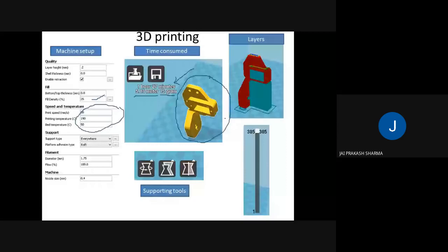There are a few tools with the help of which you can perform several things. These three tools are placed in the 3D printing software, that you can perform a rotation, because every time we print, there is a possibility that the software automatically takes a base with respect to which it is going to print, but the user can decide from which side the part is going to be printed by the printer, because it actually saves time to make these changes also.